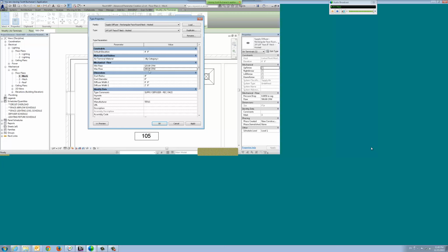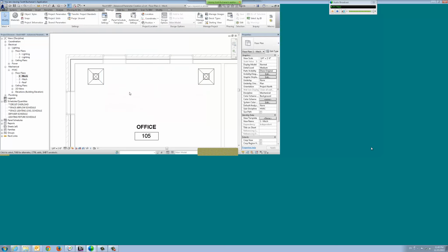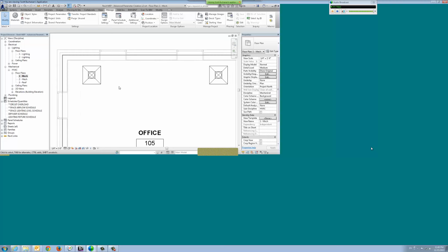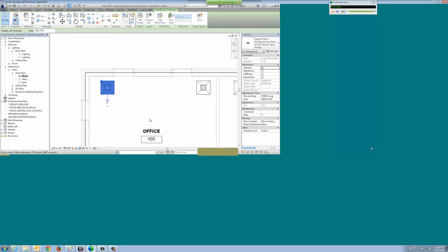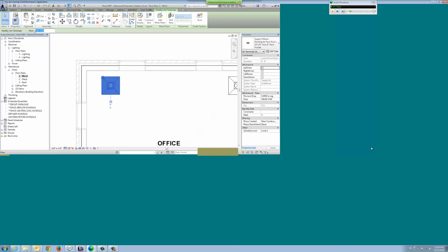let's say I give this to the project, okay? Min and max. Well, as a designer, or let's say I'm grabbing someone from the electrical group to come over and help out, okay? And they insert the diffuser, they don't pay any attention to this. Well, what else reads that airflow? Well, the duct reads that airflow, the space reads it. So a lot of things can kind of break down if we don't have the correct information downstream.